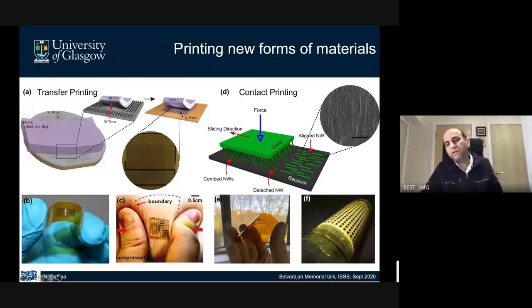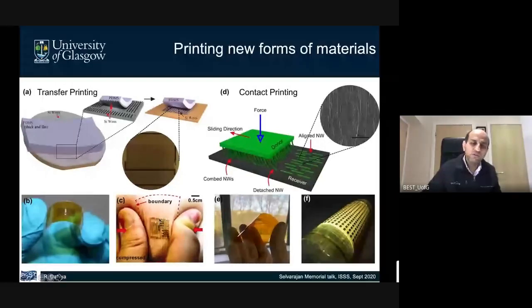And because these are micro nanostructures, because of their size, it becomes very flexible. And with that technique, solutions such as eSkin tattoo, etc., have been demonstrated. Because of their size, they can also conform to wrinkles, as you see here, because they are at nano or micron scale. But in this process, you need a carrier such as elastomeric PDMS as a transfer carrier.